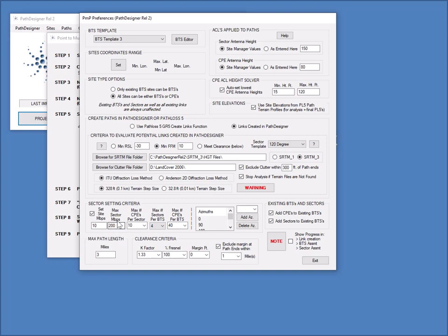We have a maximum number of megabits that a sector can support as an option, and we can set the requirement on a site to a specific value. So if I'm using 200 megabits maximum on a sector with 10 megabits site demand, then we'd only get 20 sites connected to any individual sector, which would possibly drive the need for more sectors to be added. If we turn off the site value checkbox here, it'll take the megabits value that's in the detail editors for the sites.